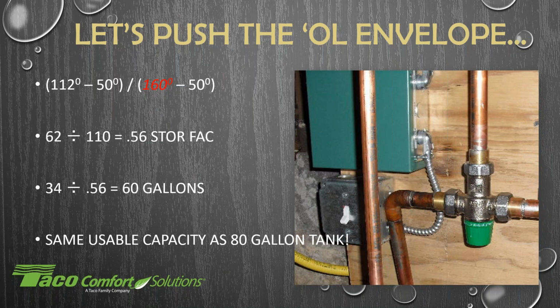Excellent. So let me just show real quick. When you take a look at this mixing valve right now that I have on the screen, coming out, heading up towards the top of the screen, that is going to your mix temperature. That's going out to your fixtures. On the left-hand side, maybe on this valve, I can't tell, I can't see the lettering, would be hot from the water heater itself. And then on the right-hand side would be your cold water supply.